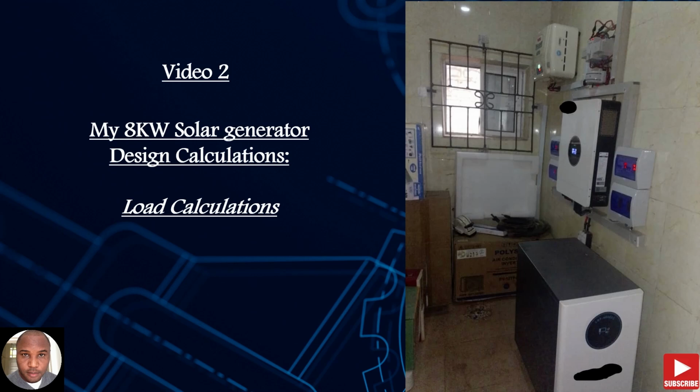Again, I'm going to be explaining what the inclination angle of your solar panel is supposed to be, because for very sunny areas like countries in Africa where you have lots of sun, your tilt angle, the tilt angle of your solar panel, is not supposed to be more than 10 degrees. Ideally 6 to 8 degrees.